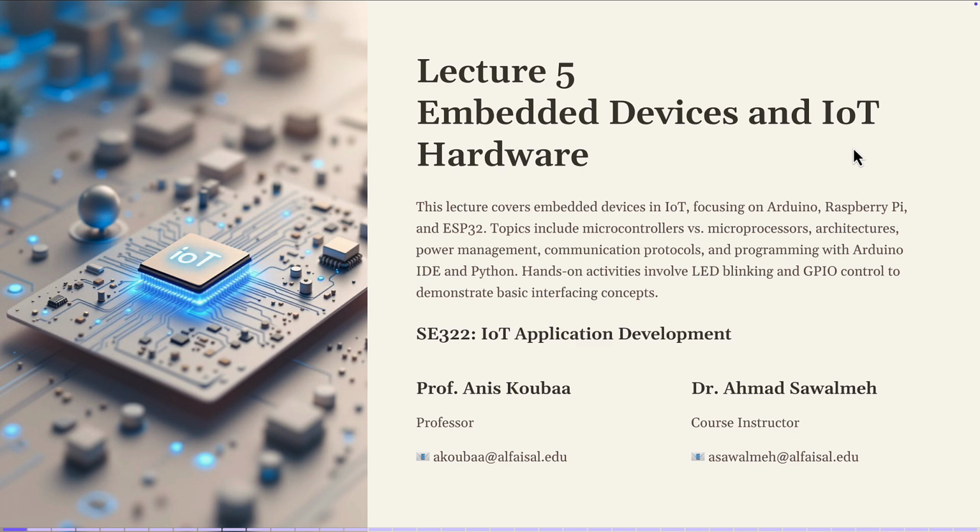Okay, so we'll introduce microcontrollers, and you will see the difference between microcontrollers and microprocessors, their architecture, power management, how to do power management with embedded devices, what the available communication protocols are, like serial communication, SPI, and also how to program with the Arduino IDE, either in C language or in Python, depending on whether you use Arduino or Raspberry Pi.